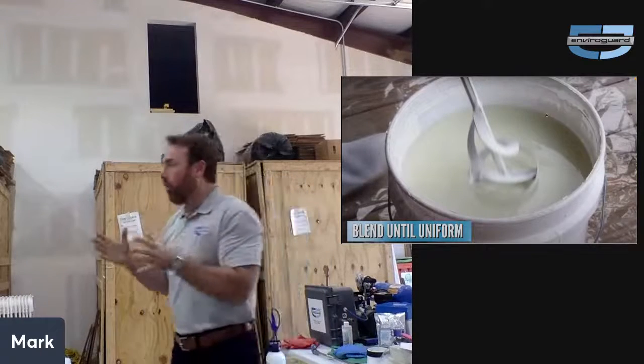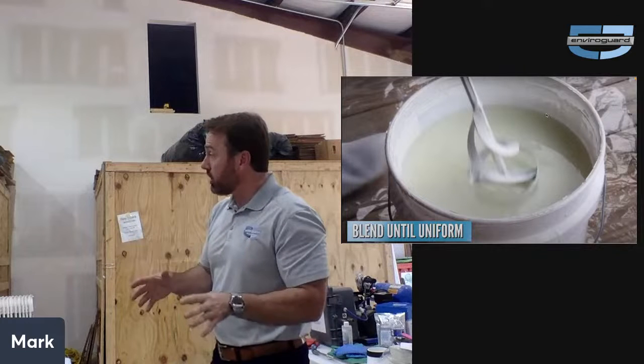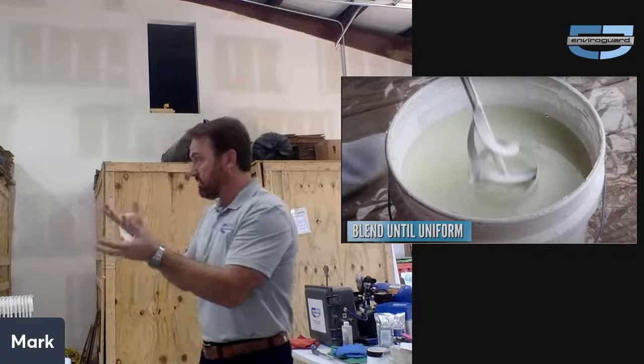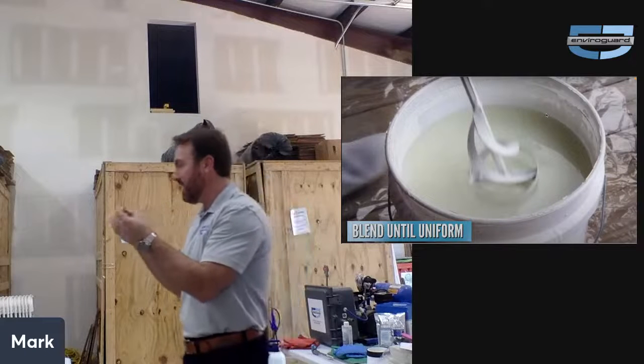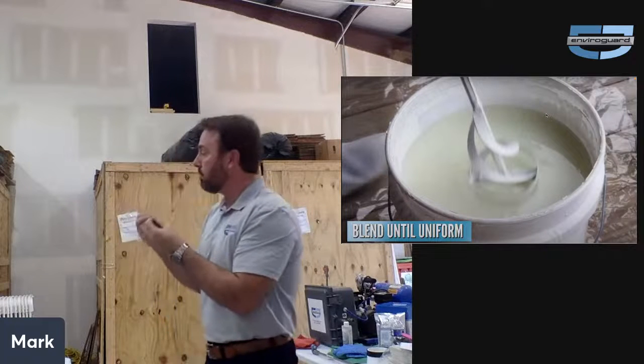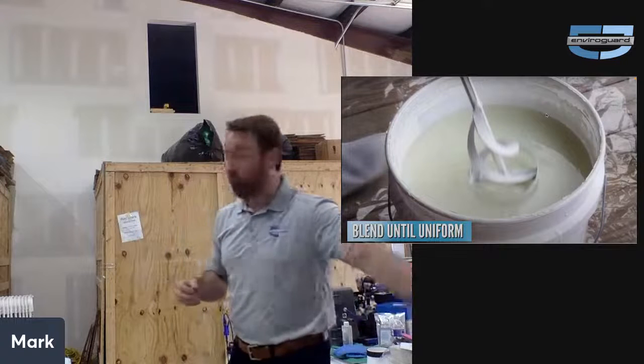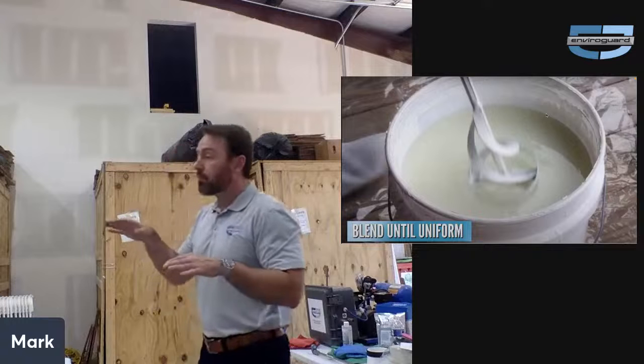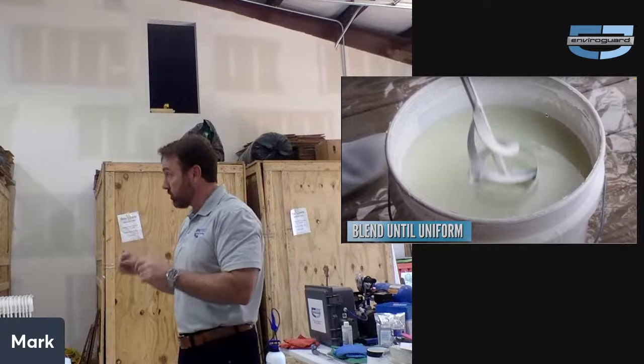Blending. You always want to blend, especially your coatings, anything that's a suspension where you've got solids and liquids coming together. So anything that's paint consistency, you want to blend it first, not only so that it's uniform, because they can separate over time, but also so you break the surface tension.